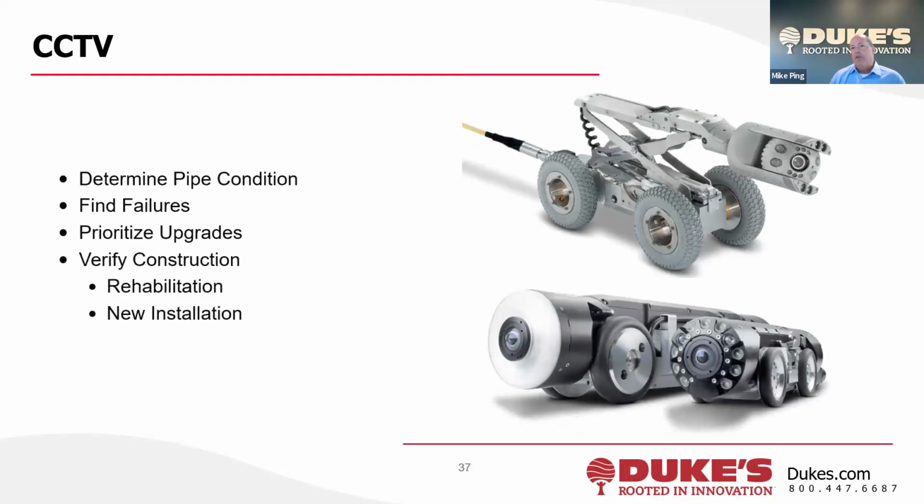Okay, so switching gears here, we'll hit on CCTV, just some example pictures of cameras that traverse through the pipe. So the reasons that CCTV happens is, number one, to determine the pipe condition, find failures, and prioritize upgrades. If you do the math, a utility can't TV and clean their whole system every year. It's just cost prohibitive. All right. So you're trying to TV, find the worst areas, and deal with those as a priority.